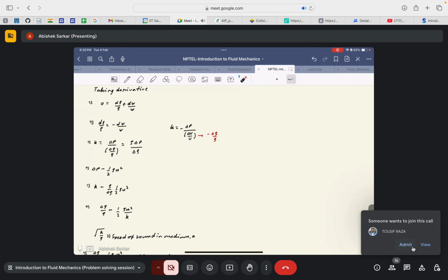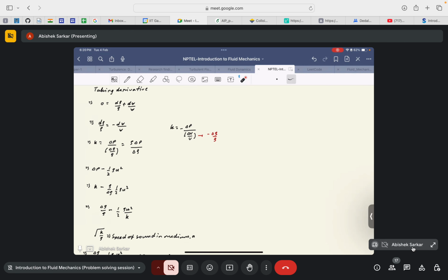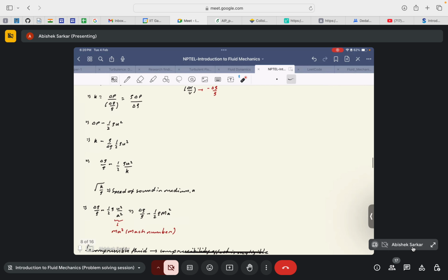Similarly, it is along the diameter of the pipe that we see a considerable change in the fluid properties, so we can consider the diameter of the pipe as a characteristic length scale. Similarly, for all other parameters such as velocity, we again need a characteristic velocity scale. And for pressure also we need some scale, like how it varies in our fluid flow.